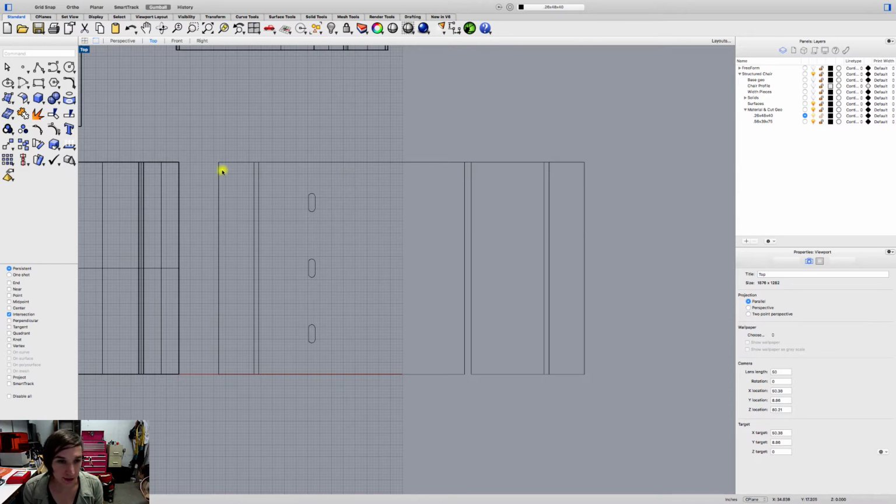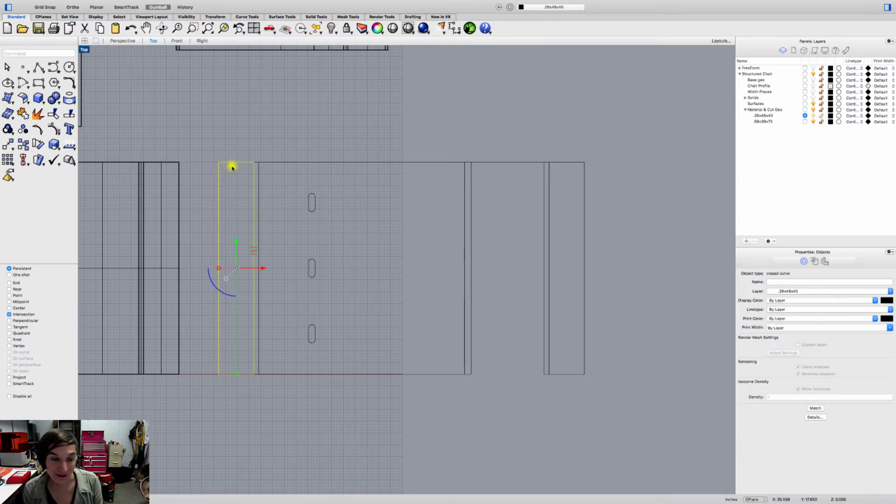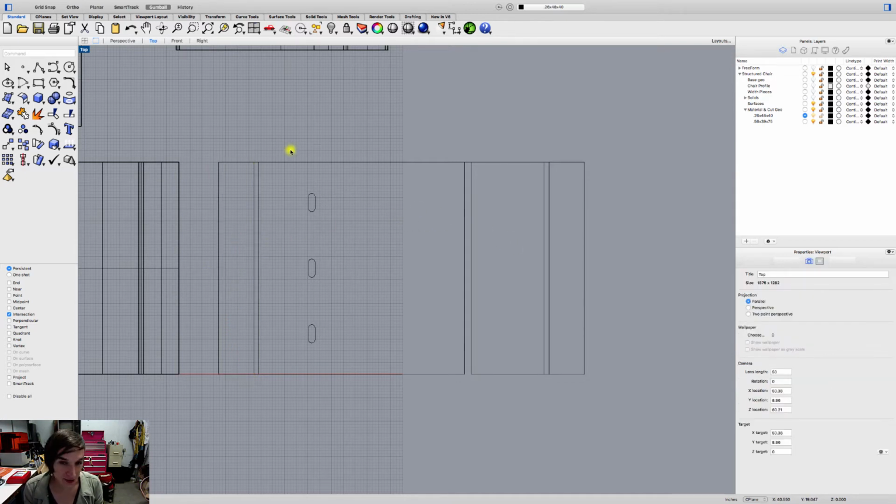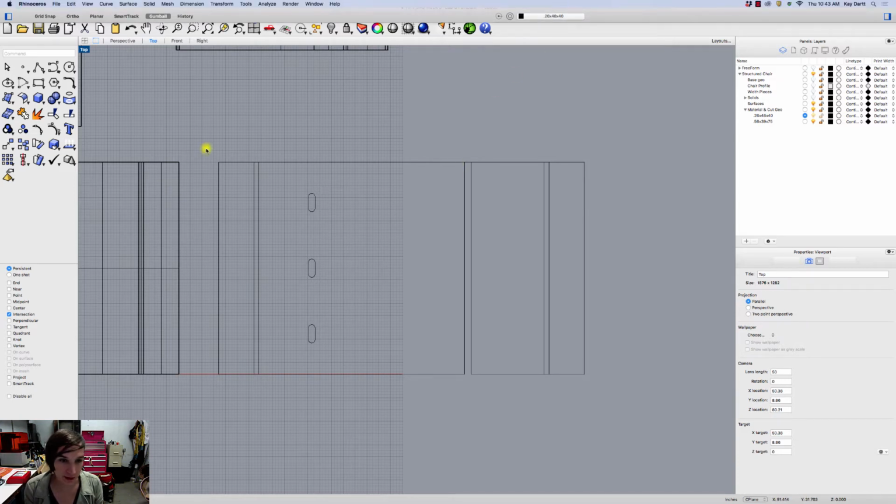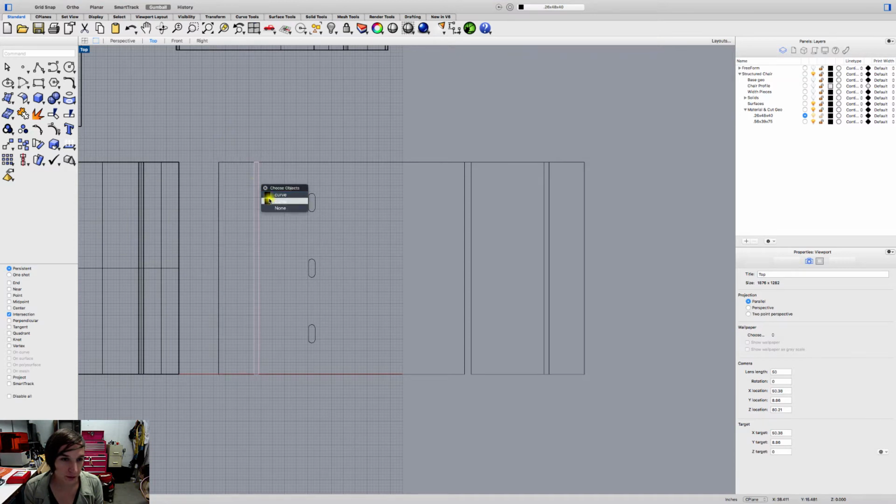How are we going to cut this out? Are we going to cut out all these individual pieces? Well, we don't really want to, because we want it to be all one solid piece that's just going to fold. One thing that can help us, though, is actually determining the lines where the folds are, right? So this is like a full fold right here. This is a full fold. And on the CNC machine, we can actually cut a little line into that so it folds nicely to just help us indicate where that's happening.